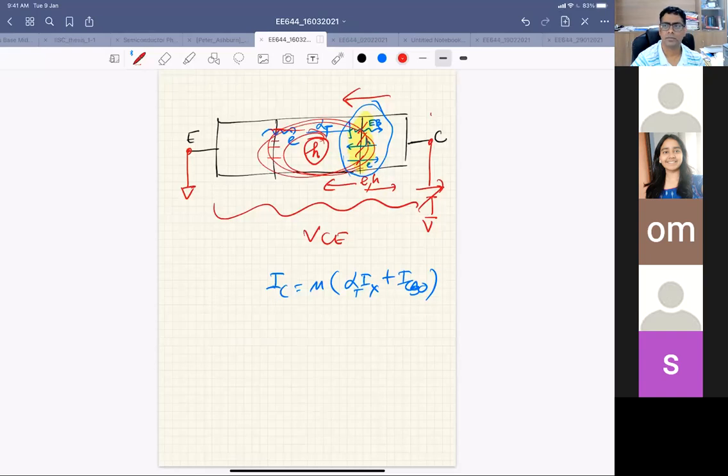Since there is forward bias, holes will also get injected to the emitter. That's the reason I need the holes to drain away. The holes themselves make it forward biased so that they can be collected at the emitter, meaning injected into the emitter. As they are injected into the emitter, the hole concentration will reduce, and the forward bias will reduce. It's a dynamic process, right?